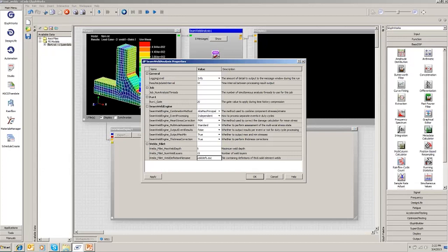Again, the stresses we're calculating are a full tensor, a 2D tensor, and so we have the option of picking weld normal, ABS max principal, or critical plane combination methods from this. And once I have this, all I need to do is go in and run, and every location that has been defined, and here I had 9 locations on the bottom toe, 9 locations on the top toe, are calculated for things such as life, bending ratio, max stress. Max stress in this case would be the structural stress, this linearized stress at top and bottom that I'm predicting.